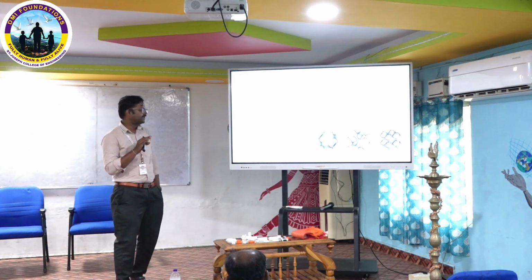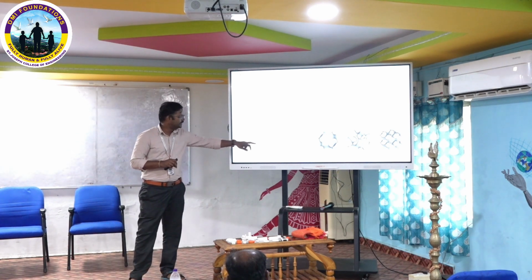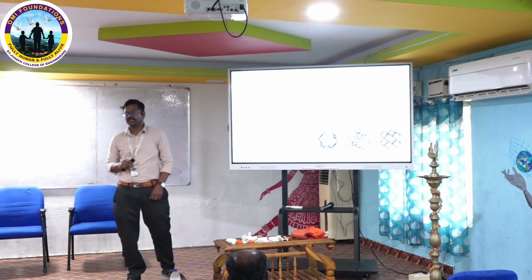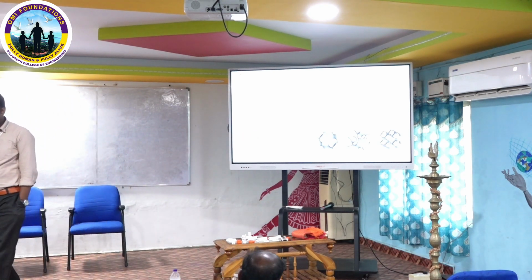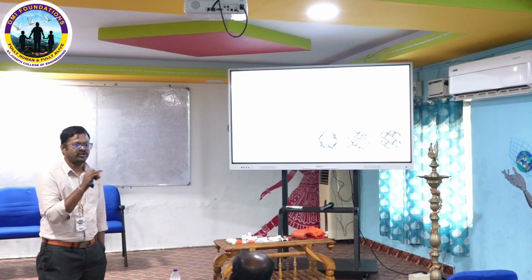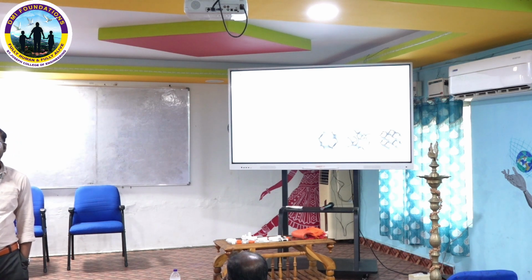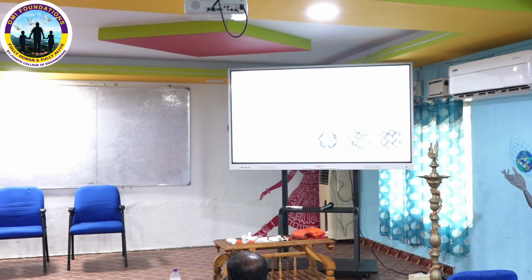Commonly we have three kinds of lattice unit cells. First is strut based, then plate, and another is TPMS. TPMS is triply periodic minimal surfaces, which are more helpful for heat transfer applications and biomedical applications. If you incorporate these structures into an implant in a medical application, it gives more surface area for tissues to grow on the implant. So it is very helpful for biomedical applications.